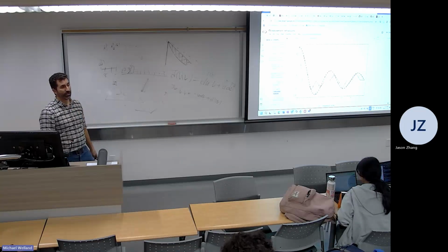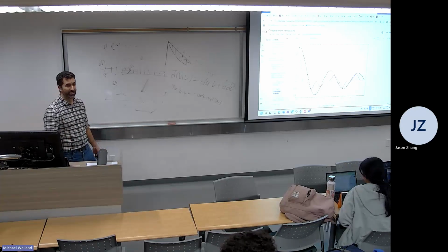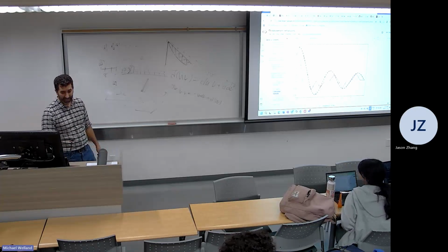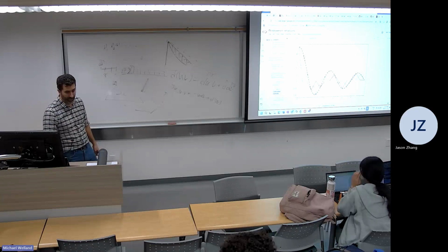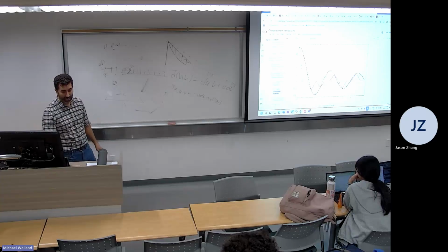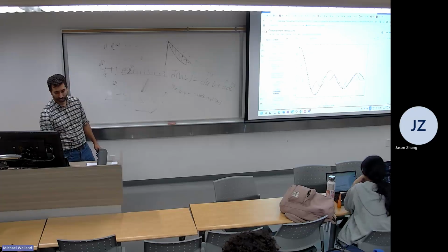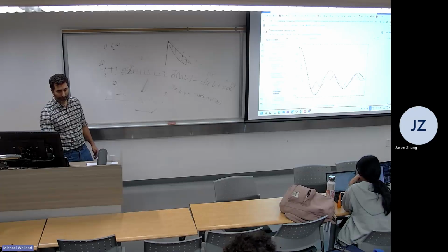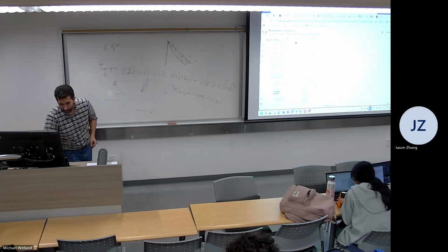This is a linear one, the most basic. It's a first order Lagrange element. They call it the tent function or a triangular function. It's 1 wherever your vertex is on your mesh and 0 everywhere else. So this orange function here is defined everywhere in your domain. It just happens to be 0 out here, goes up to 1, goes down, and is 0 everywhere else. Over here, we have a different function, which is also a triangle, right? It's negative over here, but it's 0 everywhere else. Those zeros are going to cancel out. I'm giving you guys a CliffsNotes version, and then we'll come back on Wednesday and do this a bit more rigorously.